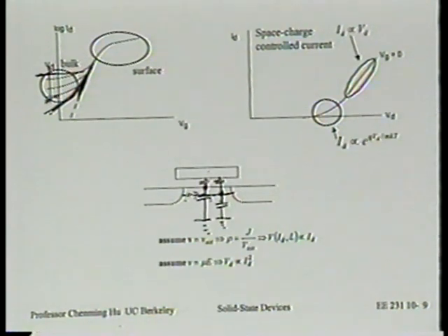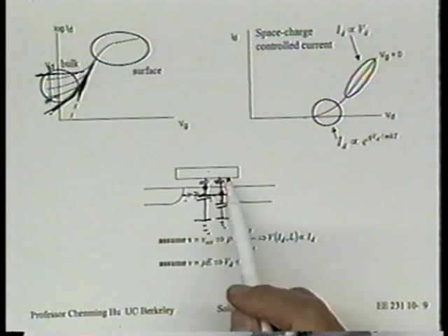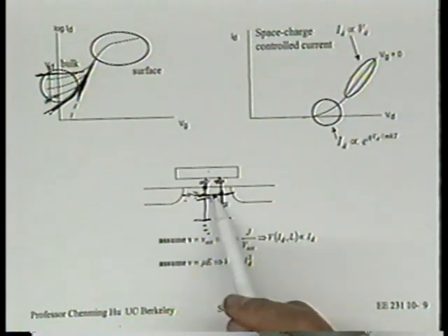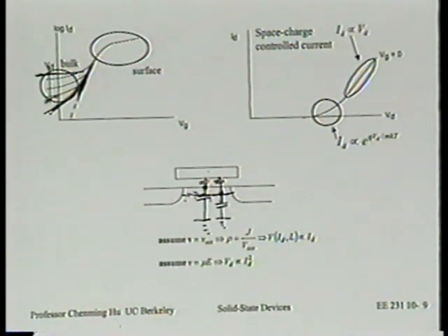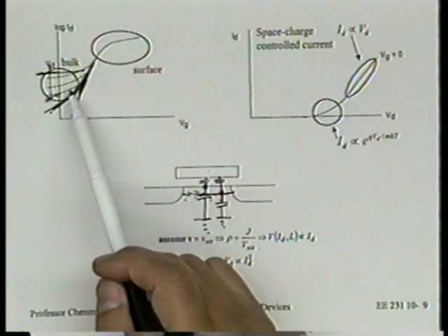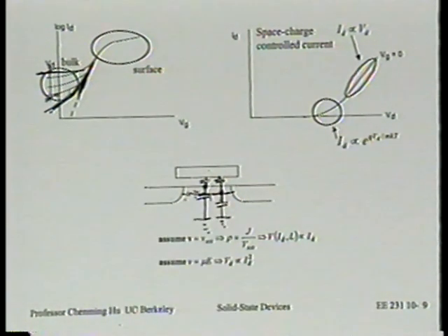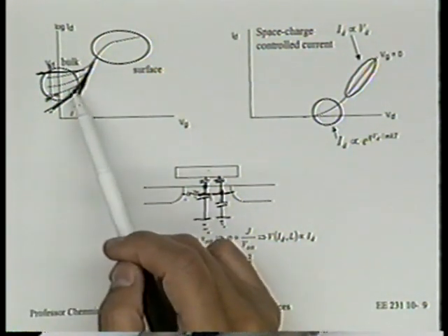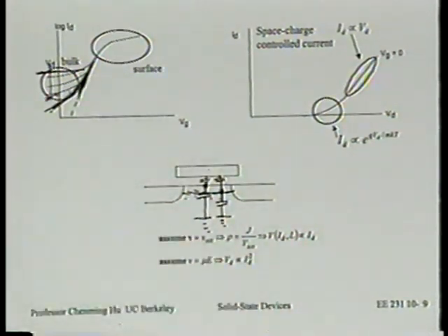Yeah, if you nod, then you understand the swing. You understand the subthreshold current, that you're not just reciting the textbook. What determines the swing is really the ratio of two capacitances that are controlling the potential at the current path. That's what it is, right? Potential will mean that barrier height, right? So this actually tells you where the current is flowing. So next time you see this happen as a result of short channel effect, you have some understanding of what might be happening, all right?